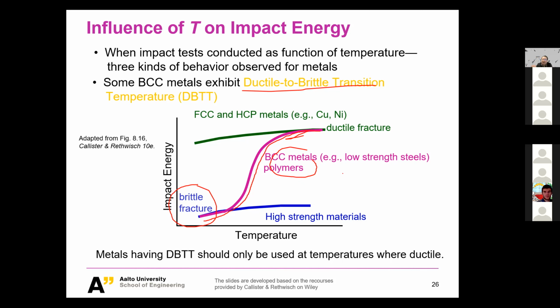So this added hardness brought by this distance requires a lot more energy to activate dislocations to move, especially at low temperatures. And that energy is, most of the time, higher than the energy your material could withdraw. And then you will first trigger fracture before moving the dislocations. So that is why BCC materials typically experience this so-called ductile to brittle transition. I hope you got it.